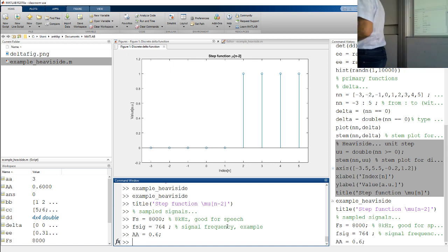And I think this A to D converter itself gives the signal range as bipolar. Okay, the lowest value is 0x000, and here we have 0x, and 12 bits is 3 nibbles.